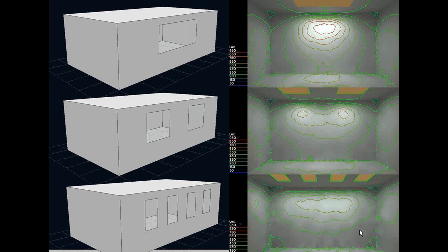The final slide shows two graphs showing the daylighting levels towards the south facade and towards the north facade. There were two options: one without overhang, one with overhang. What we were able to figure out from this analysis was that on the south facade, adding an overhang makes sense. This was a building in North India.